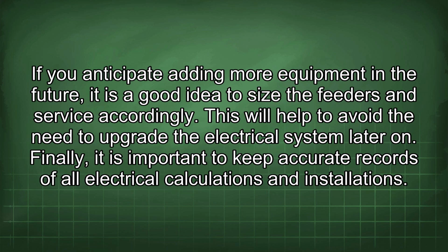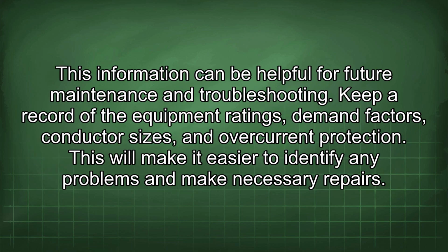If you anticipate adding more equipment in the future, it is a good idea to size the feeders and service accordingly. This will help to avoid the need to upgrade the electrical system later on. Finally, it is important to keep accurate records of all electrical calculations and installations. This information can be helpful for future maintenance and troubleshooting.